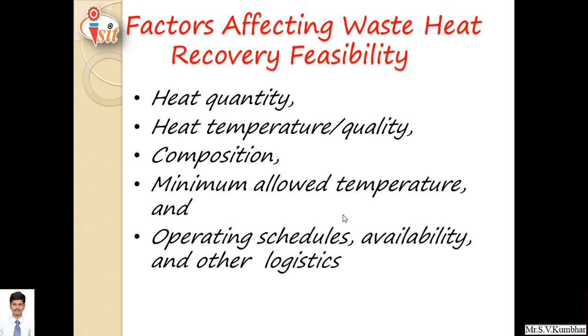Operating schedule, availability and other logistics. It means if a boiler is working continuously, then we can extract heat continuously. Similarly, if a refrigerator is working continuously 24 by 7, then we can go for heat recovery from its condenser, and we can use that heat for other purposes.